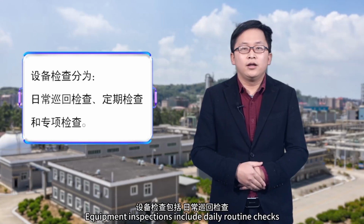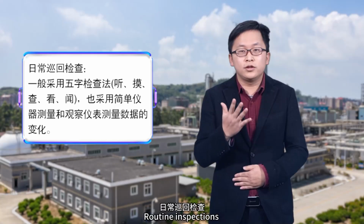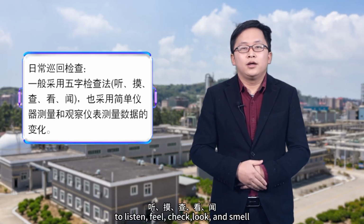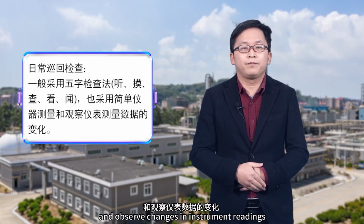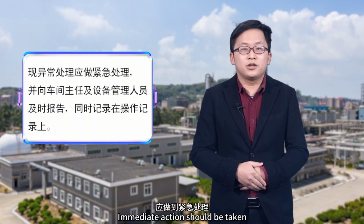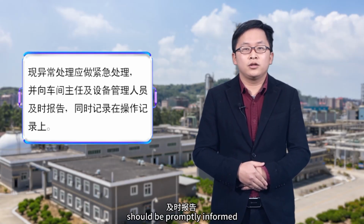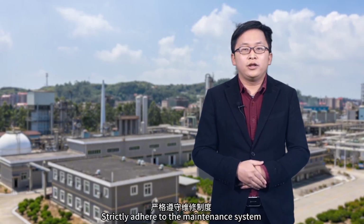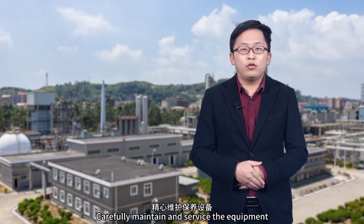Equipment inspections include daily routine checks, regular checks, and special inspections. Routine inspections are generally performed using the 5 checks: to listen, feel, check, look, and smell. Simple instruments can also be used to measure and observe changes in instrument readings. What should be done if an anomaly is detected? Immediate action should be taken. The workshop manager and equipment management personnel should be promptly informed. The incident should also be recorded in the operation log. Strictly adhere to the maintenance system during routine inspections. Carefully maintain and service the equipment.